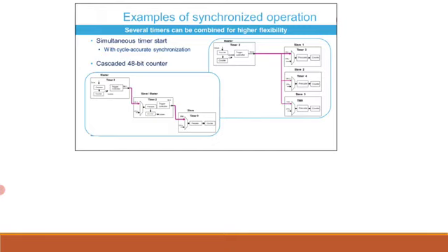A mechanism allows the master timer to start slightly delayed to compensate for the master or slave link delay and have all timers synchronized with cycle accuracy. By combining the channels of timers 2, 3, 4 and 9 as shown in this figure, it is possible to have 14 synchronized PWM channels.